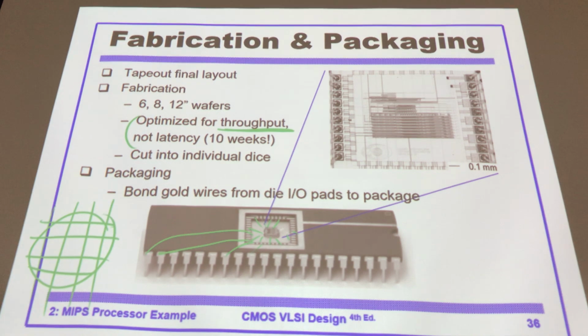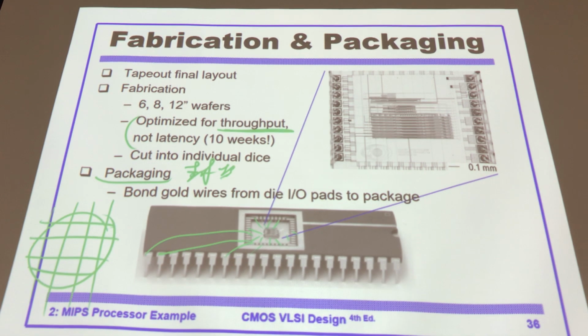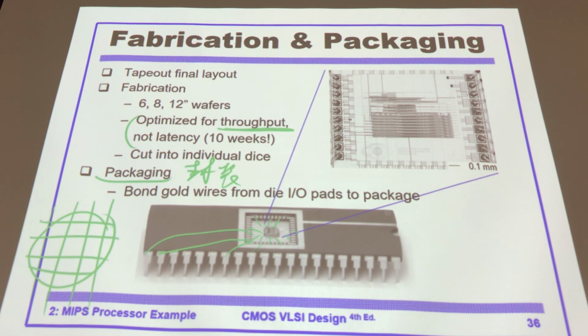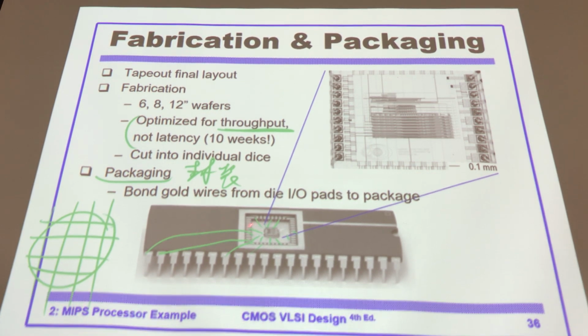But why do we need that? Why do we need to package the chip? 为什么需要封装？Well, the pin, the wire on the chip is very small, but you need to connect to the other chips on the circuit board. The circuit board is very large, the wire is very large and long. You simply cannot connect directly. You have to go from small to large.